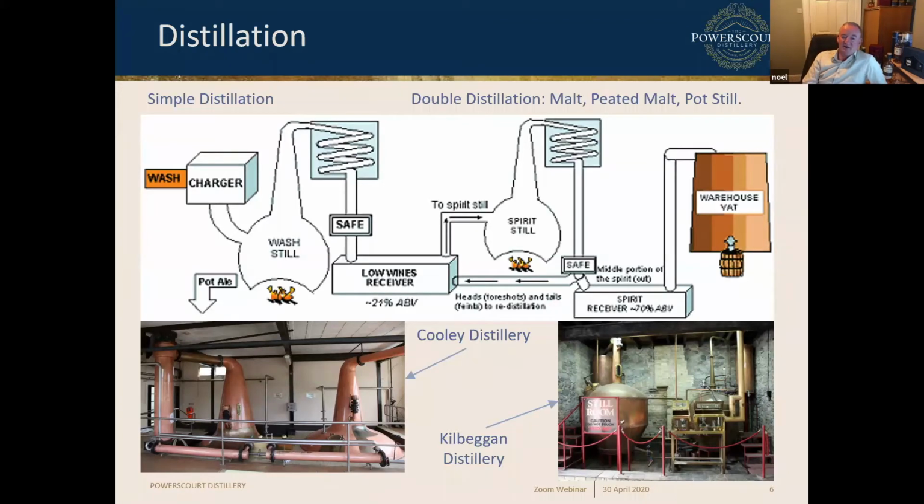those kind of high alcohols, but with very low boiling points. And the highest concentrations of those will come off the still first. As the distillation progresses, the alcohol content will reduce in the still and also in the distillate, so it will eventually end up at zero.